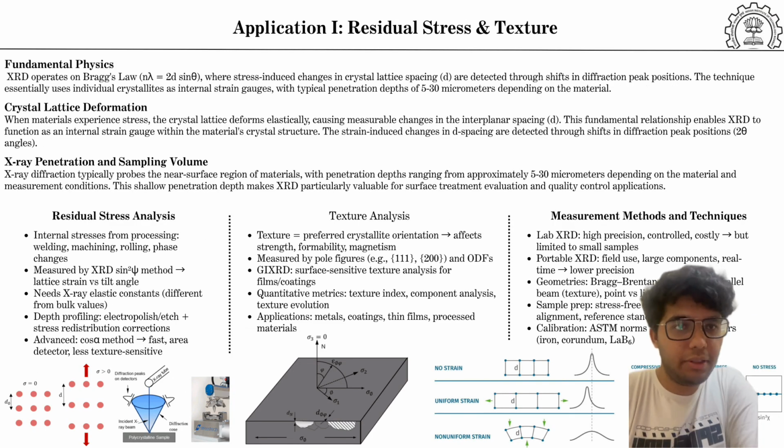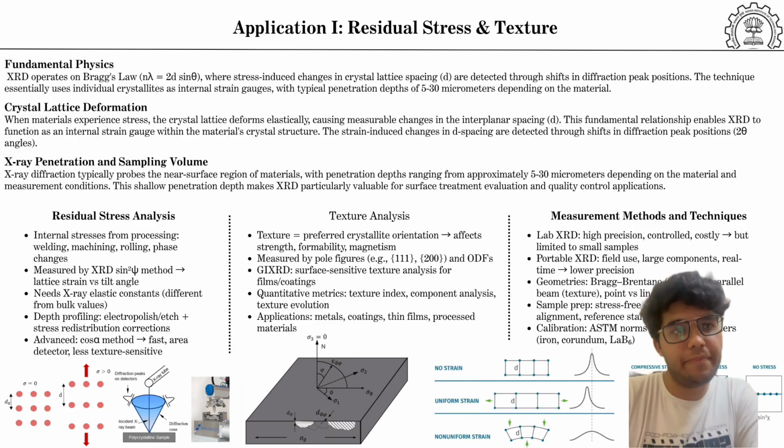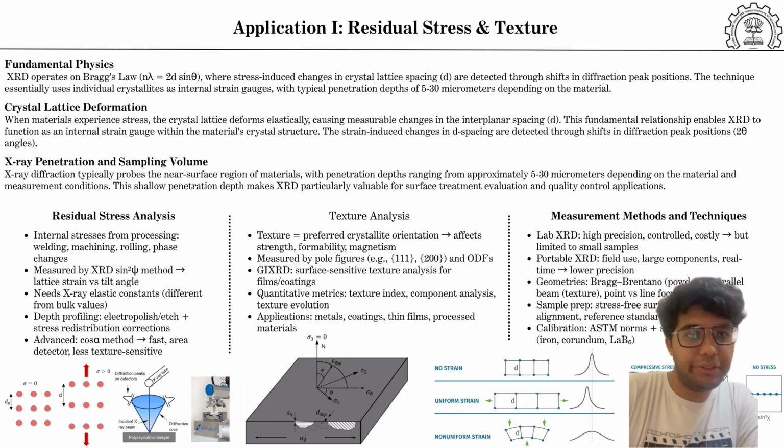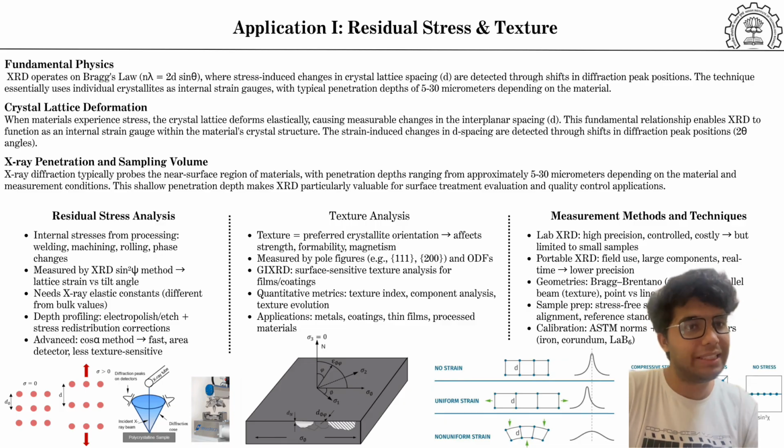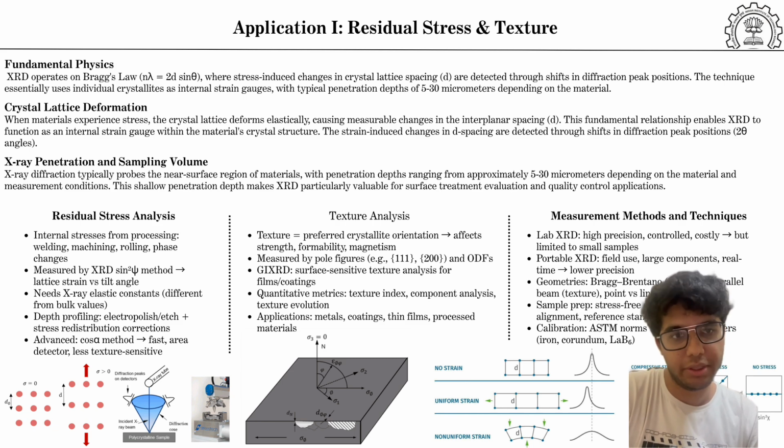Now we will be talking about the applications of XRD. First, we'll start off with residual stress and texture analysis. At its core, XRD works on Bragg's law, and any stress inside a material shifts the spacing between lattice planes. That shift shows up as a movement in the diffraction peak position. So essentially, the crystallites themselves are acting like tiny strain gauges.